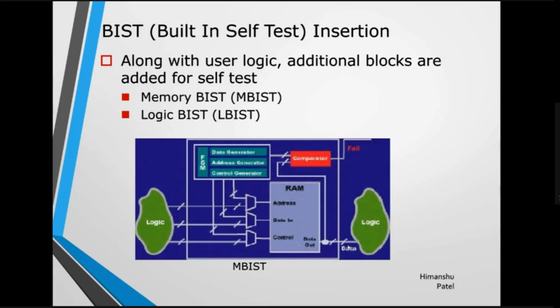To give a value to the AND gate, you need to have a storage element first. Through the storage element, you will be able to put some value there. So you have a flop. Let's say you have a flop at the inputs of the AND gate. You try to drive 1 to one of the inputs of the AND gate, and to the other input, B, you drive 0.